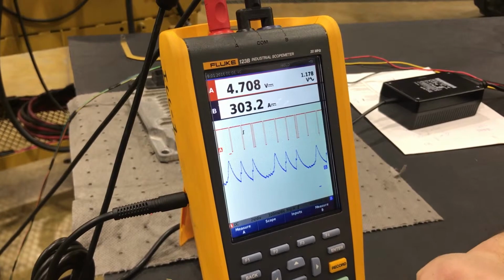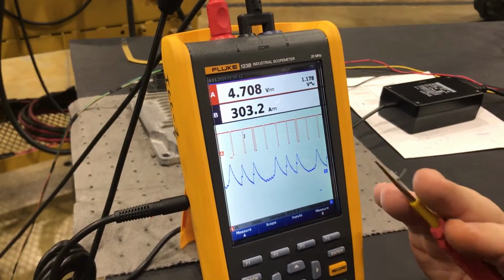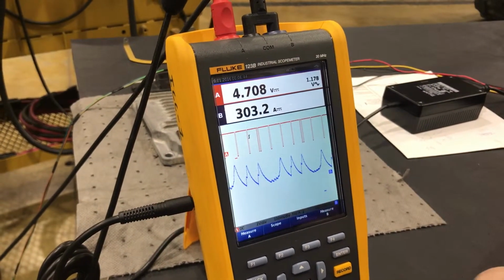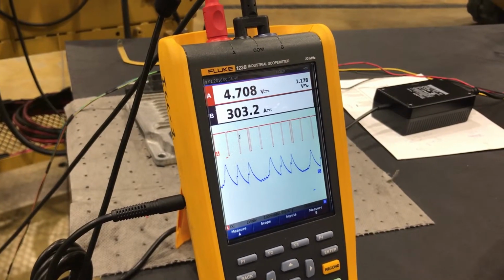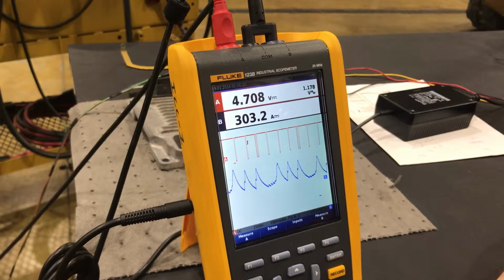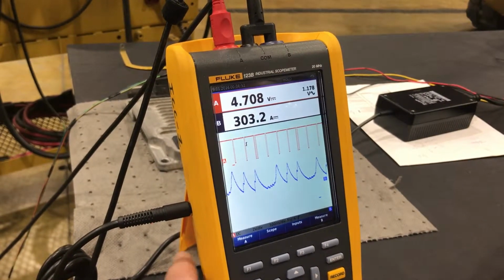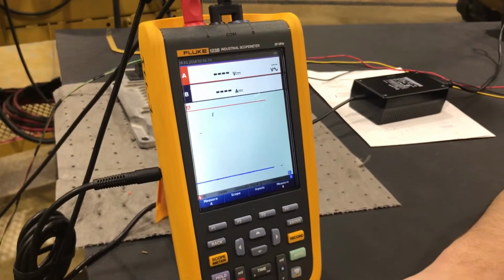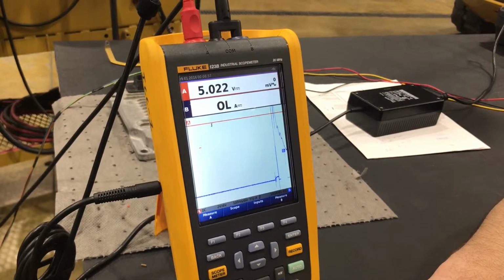Now what we're going to do is go ahead and run it. I've had him loosen a cylinder, but not tell me which one. So he put number 1 back in, and he's loosened a glow plug, but not told me which one. So we'll go to run, and then we'll have our partner go ahead and crank it.